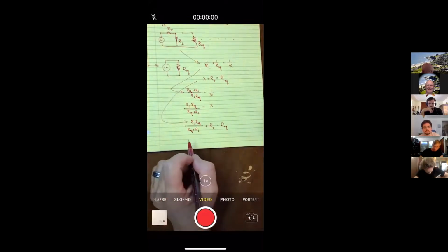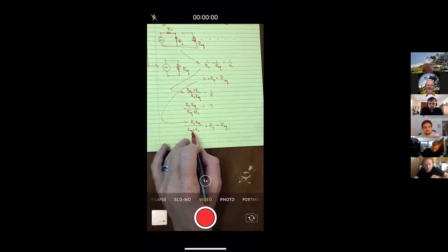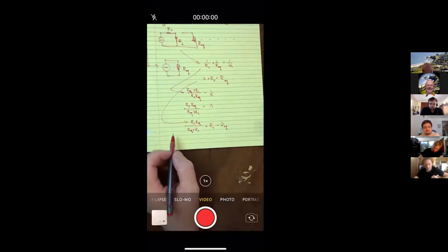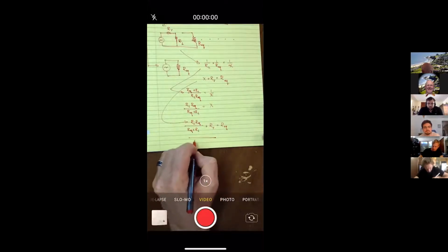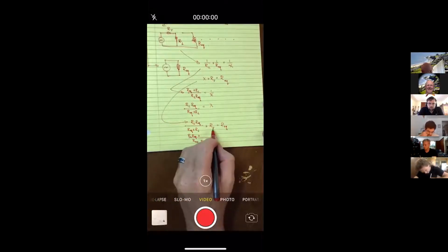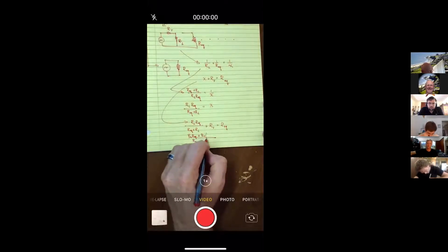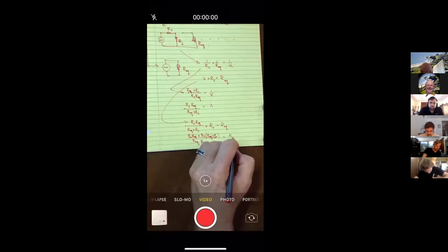And so to solve this for R equivalent, it's going to take a little bit of math because I've got an equivalent on the bottom and up on the top. So maybe I will start by getting a common denominator of R equivalent times R load. So R load, R equivalent plus, and then to get this to a common denominator, I have to multiply it by R equivalent plus R load, and that would equal R equivalent.